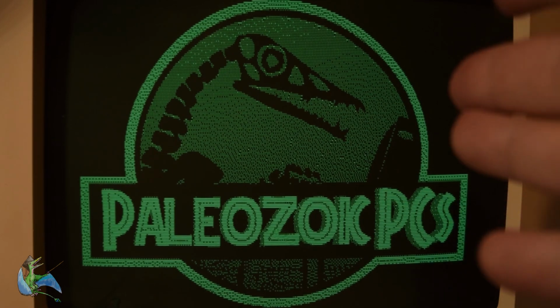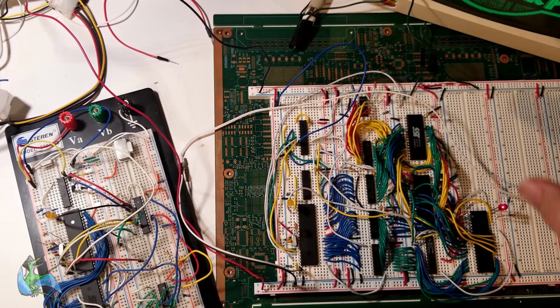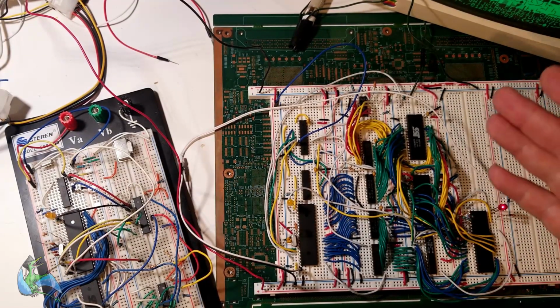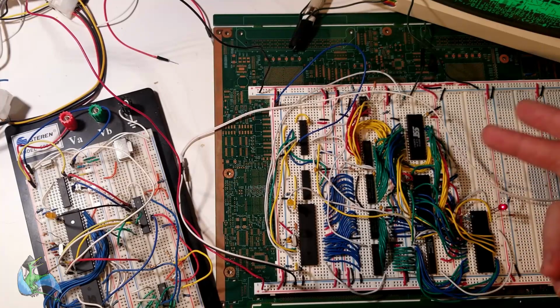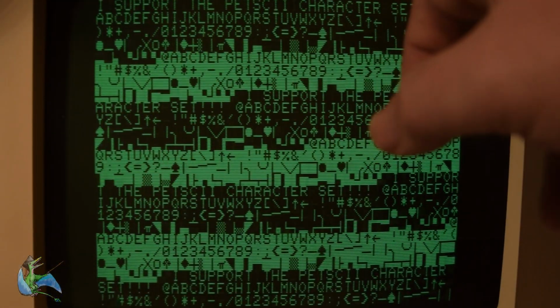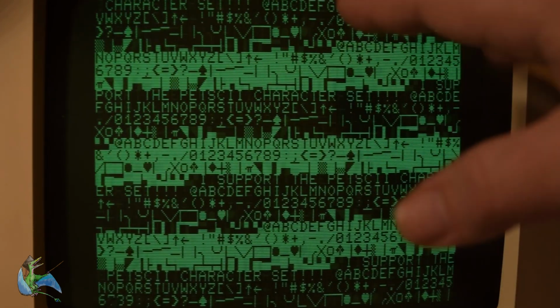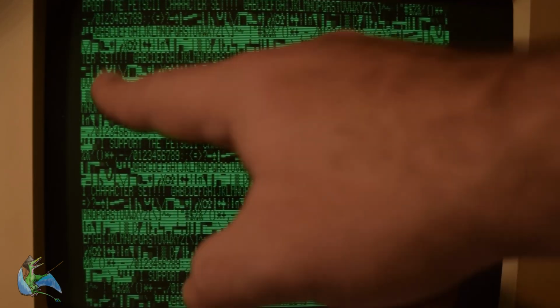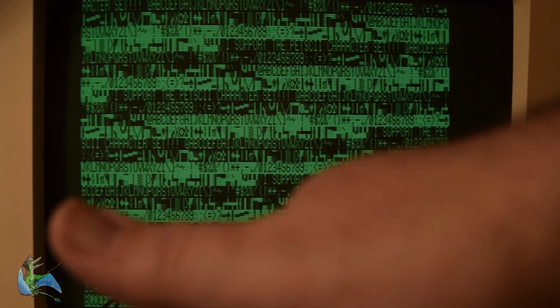One thing is, remember the indirection. When we're running in character mode, we're pointing at memory where we have the font. The data byte comes out of RAM or ROM, because in this case this is just text stored in the ROM, so it's actually hitting the ROM twice.